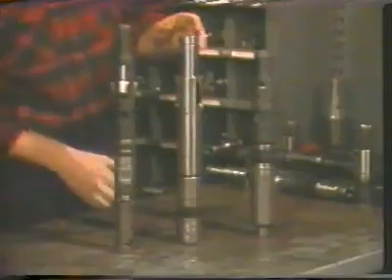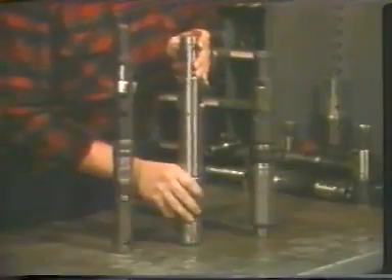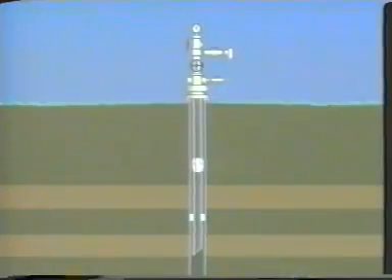One of the most common subsurface controls that is anchored by the lock mandrel is the plug. Plugs fall into three basic categories, depending upon which direction they hold pressure. There are plugs designed to hold pressure from below only, above only, and from both directions. Plugs that hold pressure from below only isolate the tubing and wellhead from the formation pressure. These plugs are used to allow removal or repair of wellheads and for safety applications when a well is not flowing but still has the potential to flow.